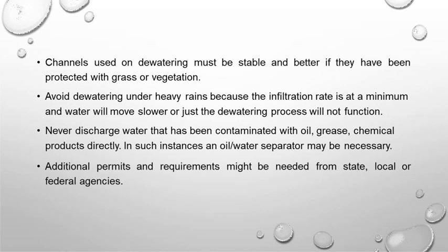Next, some information required for selecting a pump, that is, which type of fluid is to be pumped. It may be a liquid or it may be water. Next, the rate at which water is to be pumped, then the altitude of the project, then variation in water level at the suction and discharge, the pressure head at the discharge, and the size of the pipe. So this information should be considered during selection of a pump.